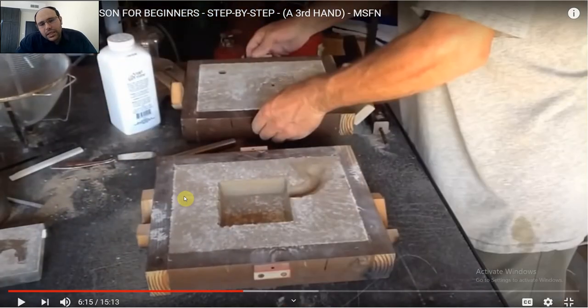Yeah, so as you can see, it is not that easy to get the pattern out. This is one of the things that you are going to study in the manufacturing class: how you can design this pattern so it would easily get out from the sand. And there are some precautions that we have to take when we get this pattern out of the sand, because if for some reason, getting the pattern out of the sand results in breaking the sand, we have to repeat the mold one more time.